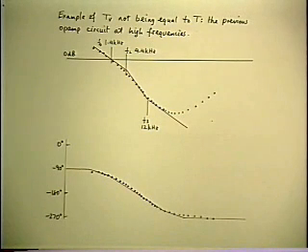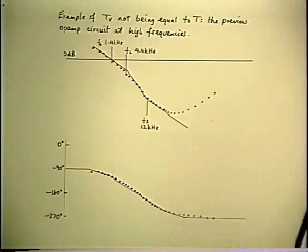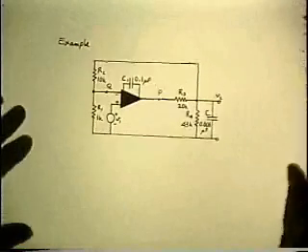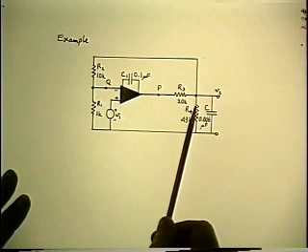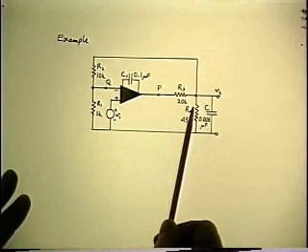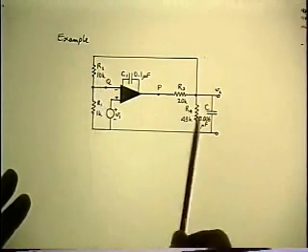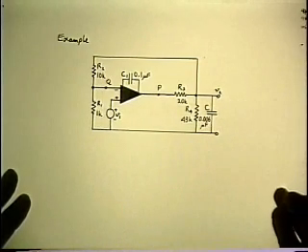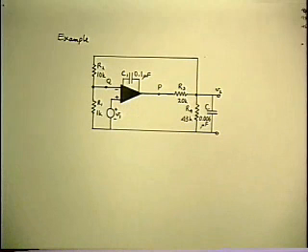Well, if the problem is that the impedance ratio is no longer small enough, since we're doing voltage injection, what we need to do is go back and actually find out what the impedance ratio is. Now remember, Z1 is the impedance looking forward. And it's easy to see from the diagram what that is. It's R3 plus R4 parallel C parallel R1 plus R2. So it's easy to figure what Z1 is. You don't have to measure it. The Z2, looking back into the IC, that's the one we're not sure about.